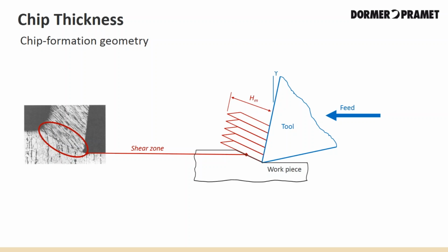When you change over to a cutter with more flutes, you have to feed it faster to maintain a particular chip thickness. Since each tooth is going to take a cut at every rotation, a tooth has only a fraction of a rotation in which to cut a chip that reaches the required chip thickness. During the time it takes to rotate and the next tooth starts cutting, the tool has to have moved far enough to shave off a chip that is thick enough, which means that tools with more flutes can be fed faster. A 4-flute end mill can be fed twice as fast as a 2-flute, all things being equal. It's important to manage the chip load to maintain the right chip thickness. If you don't, you could end up with catastrophic failure.